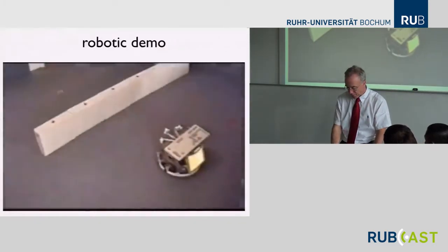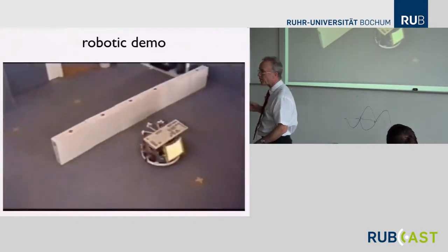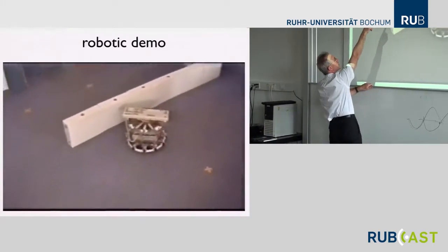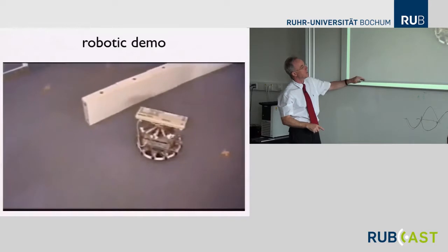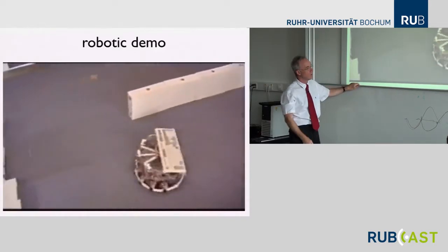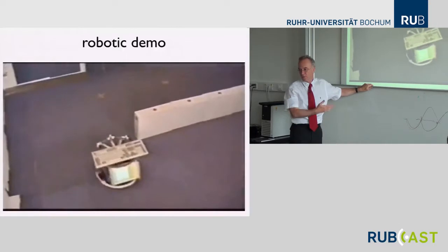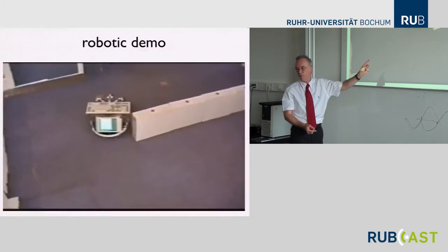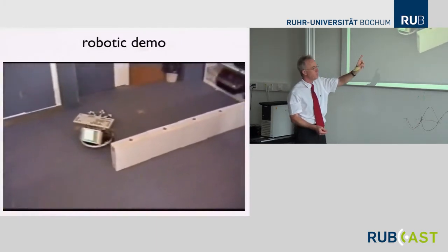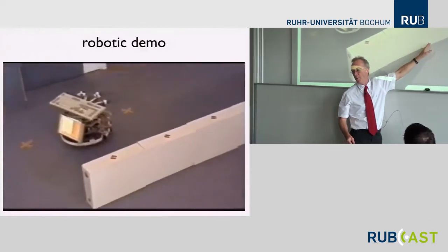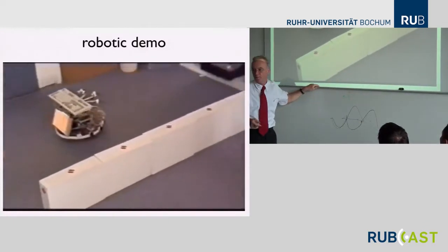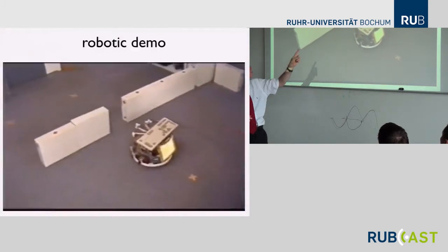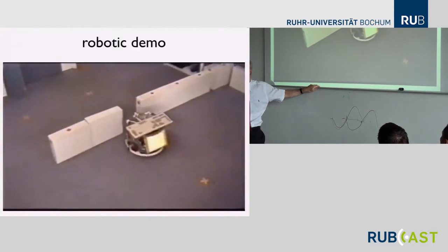I have here an example. This robot, I have to explain in a second how it actually works. So this robot wants to move to this target. This little cross up there has these obstacles. It's a very simple local algorithm, essentially implementing what I just did. And this is a demonstration that we tuned the parameters right. We make an opening of different sizes, and then we make sure by parameter tuning that the bifurcation happens when that opening is large enough for the robot to pass through.